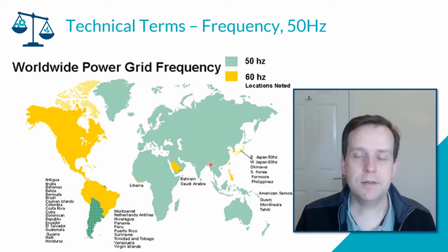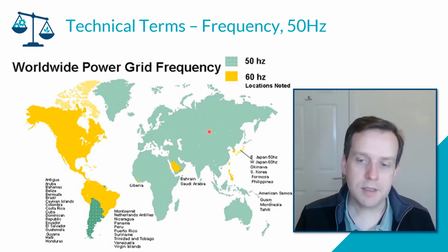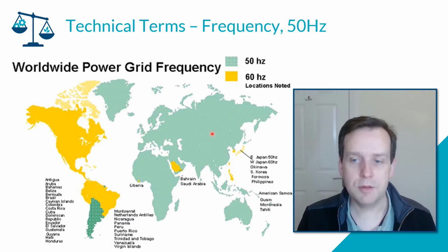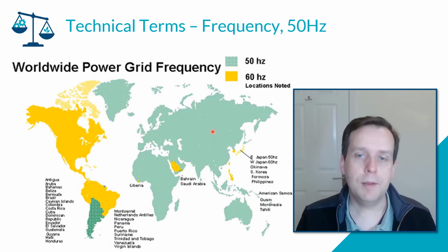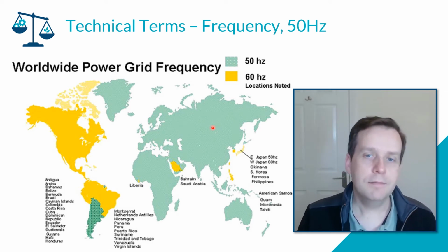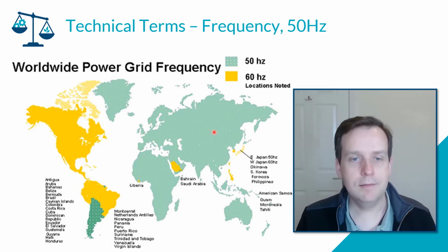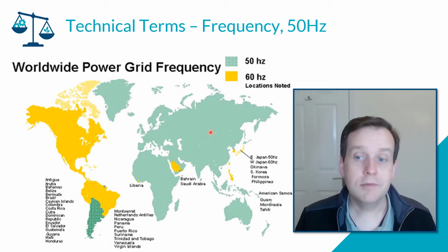Any faster than 50 or even 60 hertz, then you have mechanical problems with the machinery, because 50 hertz means 50 times a second. To have a big machine rotating faster has mechanical problems. So 50 hertz or 60 hertz was chosen as a suitable band to compromise between flicker and the mechanical issues of a big machine going that fast.